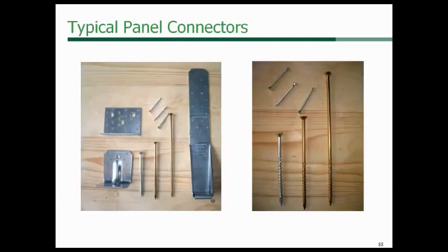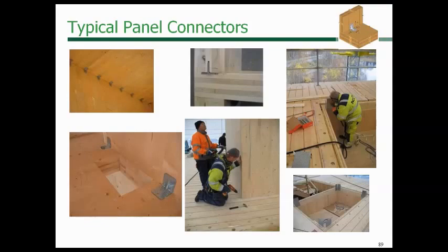The typical panel connectors that are for floor-to-wall connections are not unlike what we're used to seeing for wood connections. Lots of lag screws, angle brackets for floor-to-wall connections. These screws are generally self-tapping. They go in fairly easily as long as you can put them in straight. And it really allows you to put these buildings up really quickly.